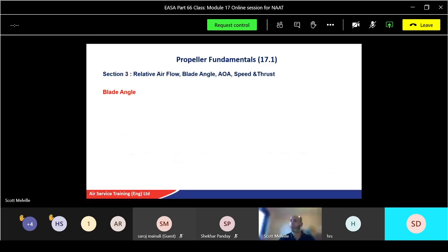Have a look. So again, there's a standard airfoil, and we've got our vectors. Let's put some information on there. So thrust is going forward. Now remember, that'll be felt on the underside here. Thrust in Module 8 was lift. So the propeller blade, as it's spinning round, is producing lift, but as we know it, we now call it thrust, hence a change in the vector terminology.